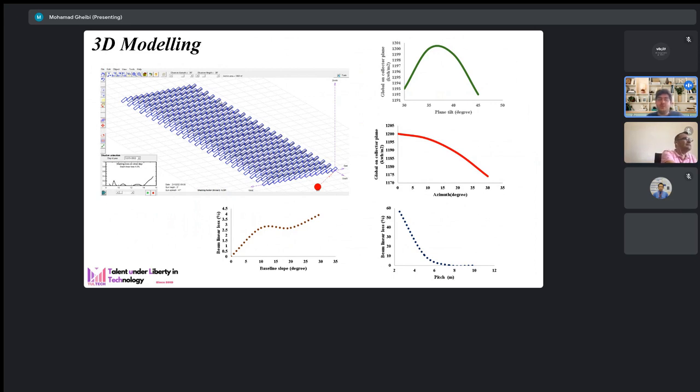If you have shadow, even in 25% area of this panel, depending on the panel type and the material used inside of the panel, you cannot provide any energy, and it is a disaster.